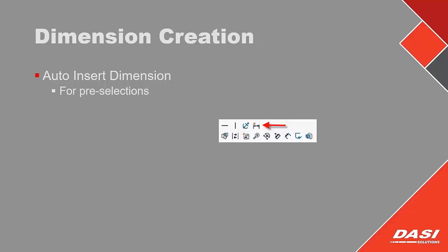All right, so for SOLIDWORKS 2018, we've seen enhancements today for bounding boxes, the ability to create bounding boxes on singular components, the ability to do mirrored components inside of assemblies where we transfer the material and propagate the visual aspects from the original components. We saw some improvements to the performance evaluation tool, as well as new enhancements for drawings.